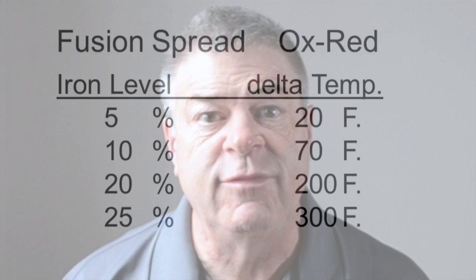One of the things that we have to recognize is that low NOx firing generally likes to take the oxygen out of the system and create a high carbon monoxide environment. Not only will carbon monoxide take the oxygen off of iron, it also takes the oxygen off of nitrous oxides. So you can lower NOx by having the presence of carbon monoxide.